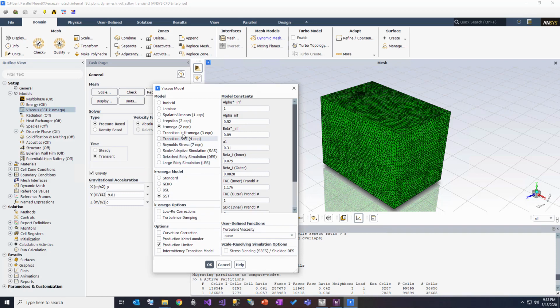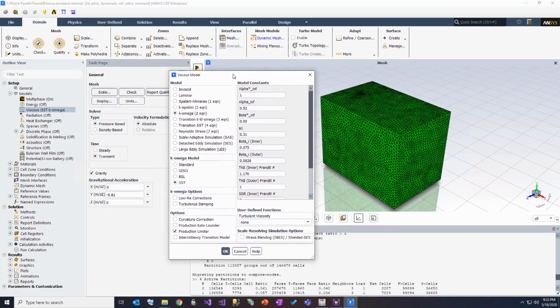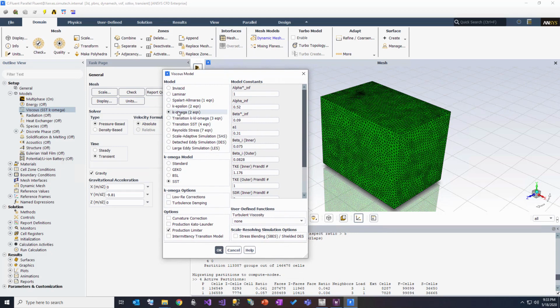The thing with that is if you're going to higher quality turbulence models, you have to make sure your mesh is appropriate for that. In our case, since we're using a demo coarse mesh, it's good enough. K omega SST is a good enough model to capture that, and we shouldn't really be using any other models with higher order resolution since the mesh is not there.